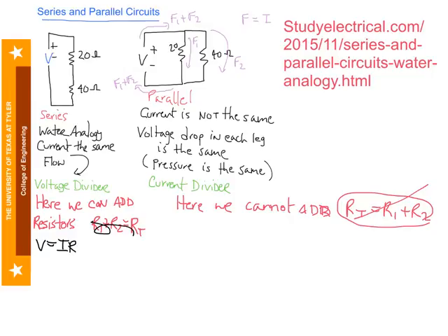and we did this in the last little part of this lesson. So let's say we have a 6-volt battery. So 6 V for volts equals I, and now we look at our resistance. If we add R1 plus R2, we have 20 plus 40, that's 60 ohms. I can find the current. So I is equal to 1/10 of an amp, right? 0.1 amps.